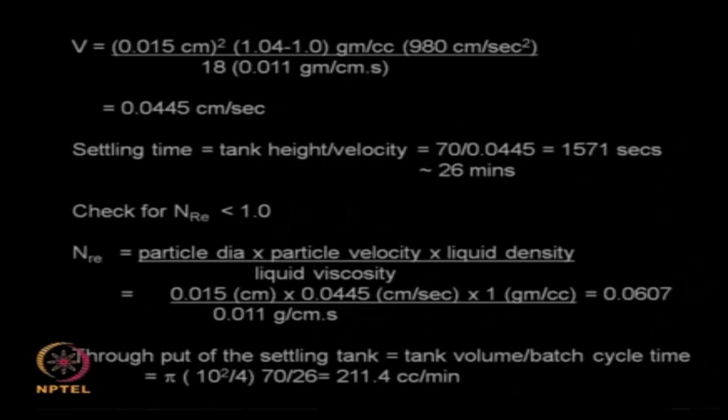So Stokes law depends upon dilute solutions, that means the solids that are settling down are not disturbing or impeding the other solids present. One solid may affect the movement of another solid either through collision or creating eddies or turbulence, and then we cannot use the assumptions of Stokes law. That means if the concentration is very high we cannot use the Stokes law. If the velocities are very high in the form of turbulence, then again Stokes law is not valid.